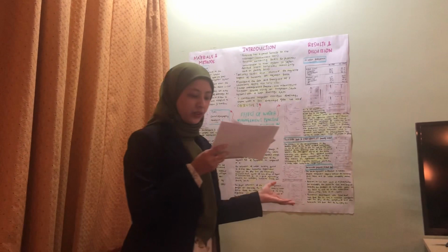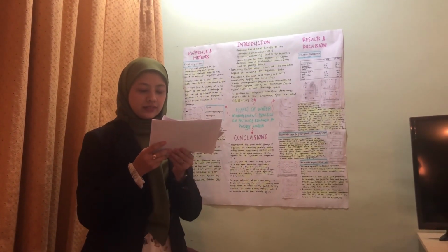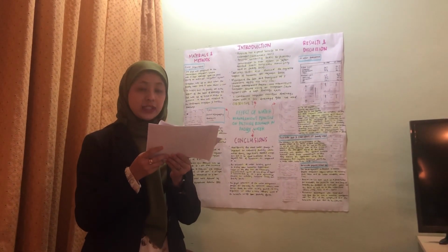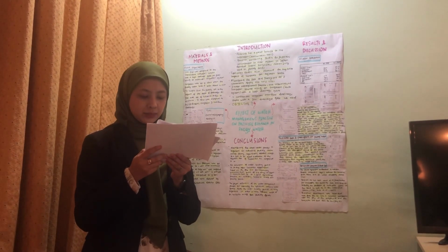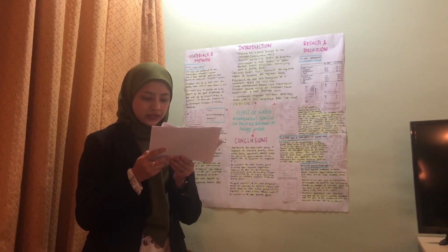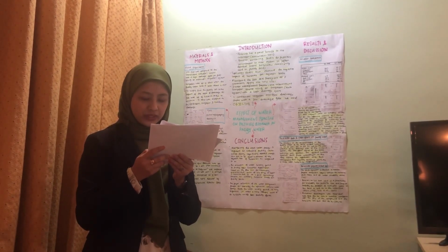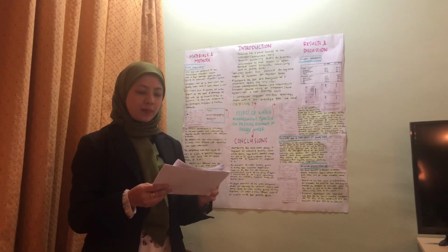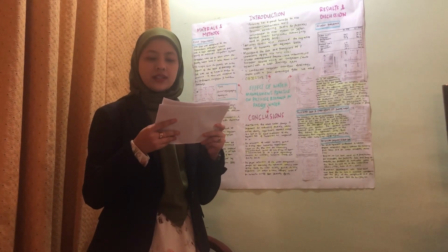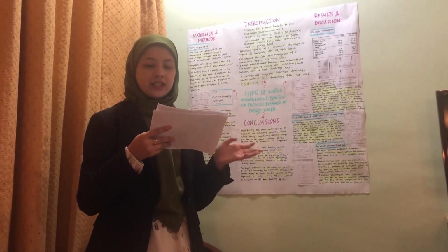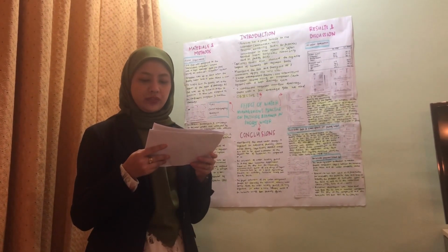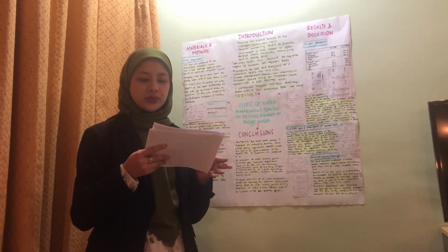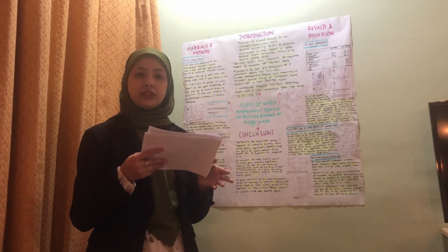Newly irrigated water therefore swept the standing water, which contained a higher concentration of herbicide, towards the drainage gate, creating a spatial variation in the herbicide concentration within the plot. It was also reported that the paddy plot with a similar setup and a high drainage height of 7.5 cm in 2001 had neither paddy water runoff nor herbicide runoff, due to sufficient excess water storage during the monitoring period.